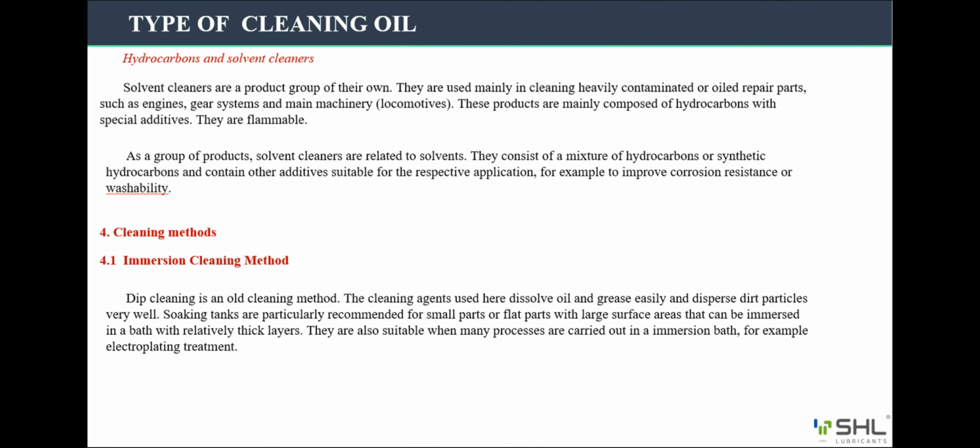Next, hydrocarbons and solvent cleaners. Isoparaffins are the most commonly used hydrocarbons for metal cleaning. Advantages are relatively low cost and easy disposal. However, when using these substances, the risk of fire and explosion must be taken into account.